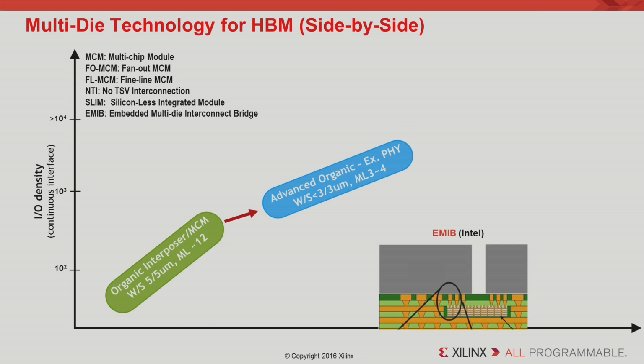The interesting thing about this option is it's supposed to reduce the cost compared to a silicon interposer because the silicon is used only at the interface region, therefore reducing the area. But there are still some more challenges around how you maintain the coplanarity of the substrate and the bumping itself during the assembly process, right?